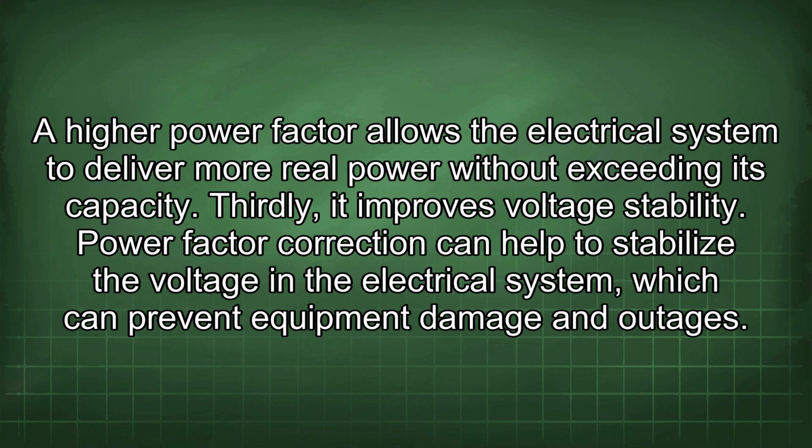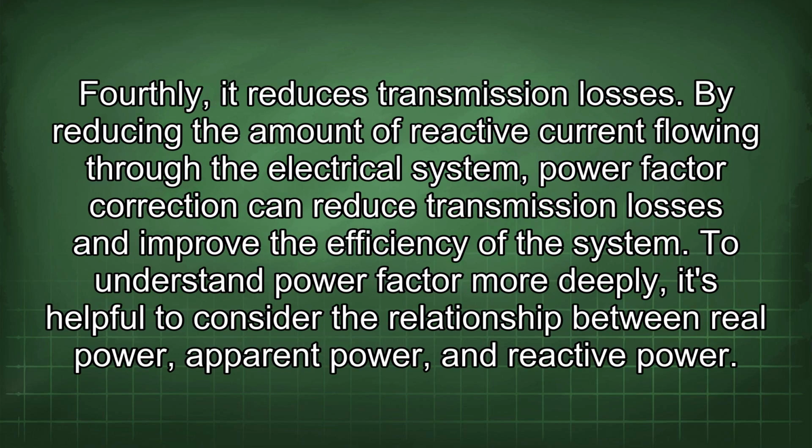Thirdly, it improves voltage stability. Power factor correction can help to stabilize the voltage in the electrical system, which can prevent equipment damage and outages. Fourthly, it reduces transmission losses. By reducing the amount of reactive current flowing through the electrical system, power factor correction can reduce transmission losses and improve the efficiency of the system.